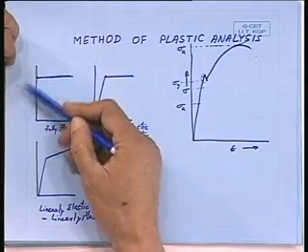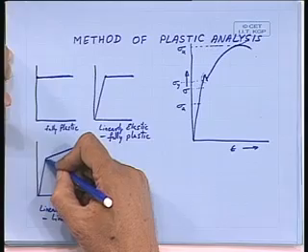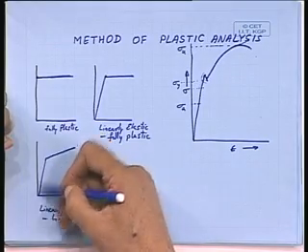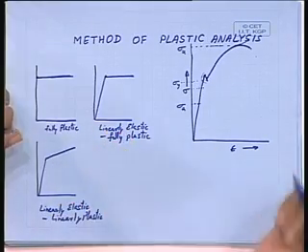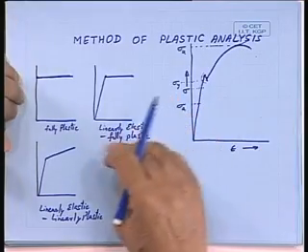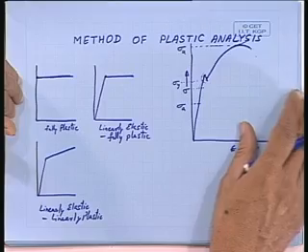In fact, this type of material one uses in concrete. You assume that the concrete does not deform till it comes to some sort of a breaking limit. And we want to keep some as reserve, and we will not consider it to be linearly elastic, linearly plastic. So we are left with only one choice, that we assume that the material is linearly elastic and fully plastic. So we will concentrate on this, and on this basis we will try to see what happens.